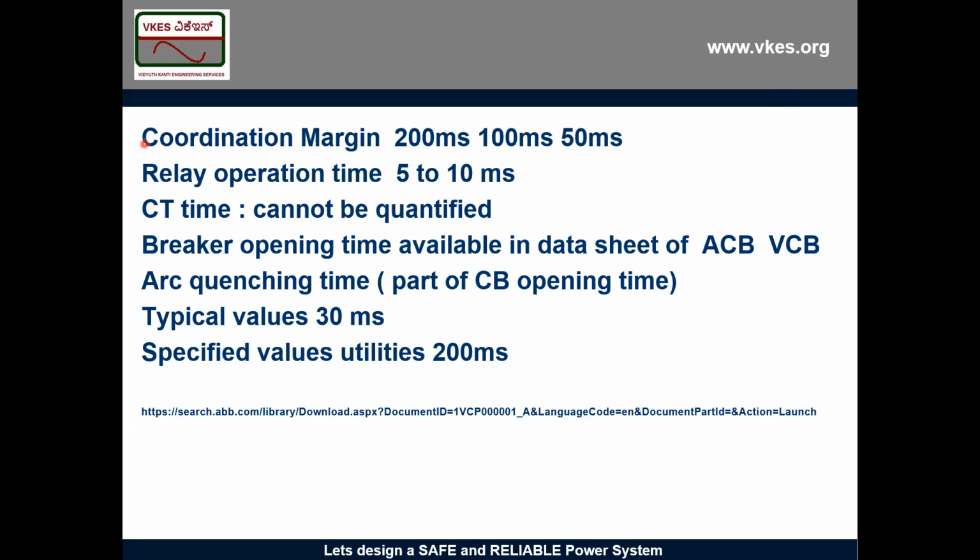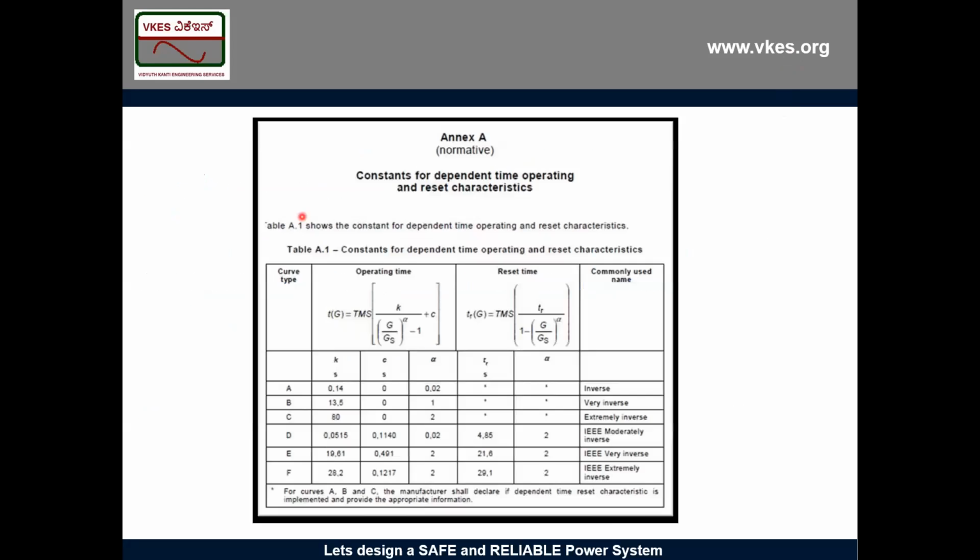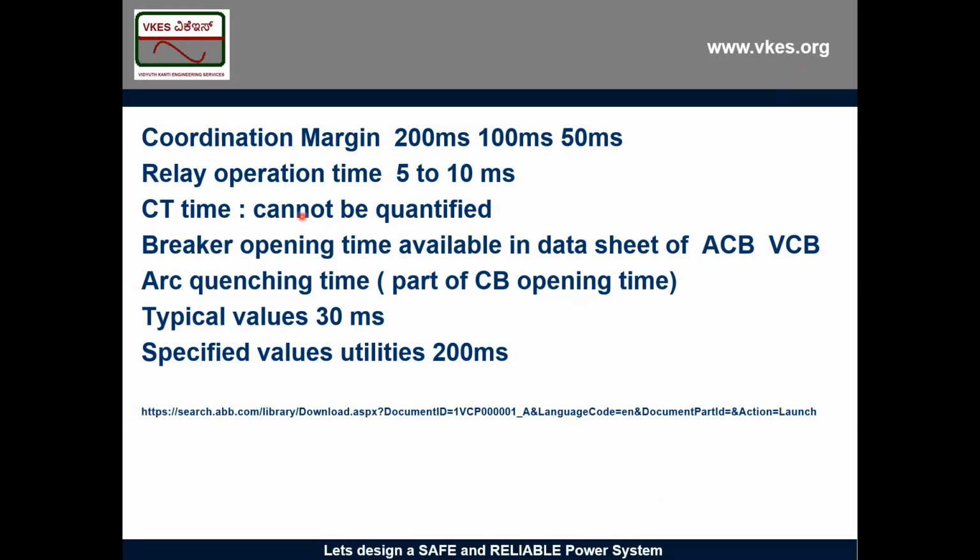Yes, sir. So, what is this coordination margin? Anybody can tell? Mr. Pinaki, what is coordination margin? It is the gap in time between the equipment you want to protect and the relay operating time. Like the curve of the relay and the curve of the equipment. That time gap is your coordination margin.